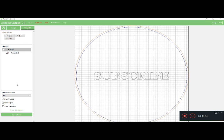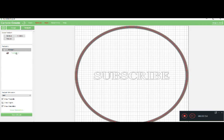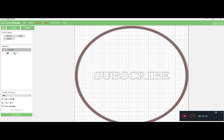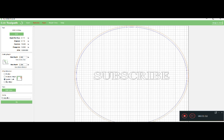If I just hit OK, you're going to see it's a toolpath. Toolpath number 2. This is what I'm clicking on, and it's showing the toolpath. So we're going to go toolpath, and we're going to go no offset, just like I was showing you, instead of pocket or outside. We're not going to do that. We're going to do no offset. How deep do I want to go with this cut? Do I want to cut it out completely, or do I want to only cut down a certain amount?